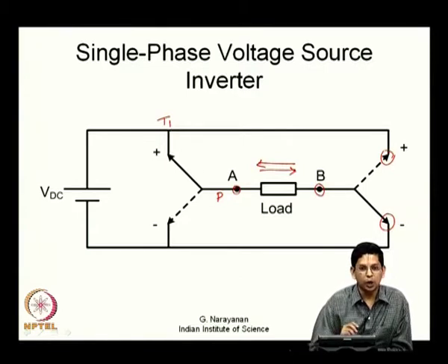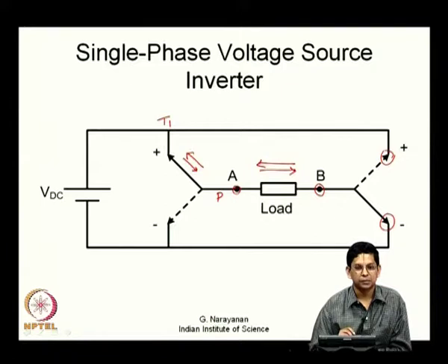Between P and T1, what do we want? We want a switch which can conduct in either direction. The direction of conduction will depend upon the load current. So, we want a switch which can conduct in either direction.